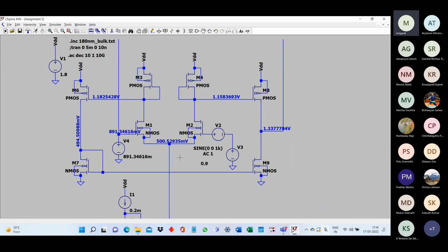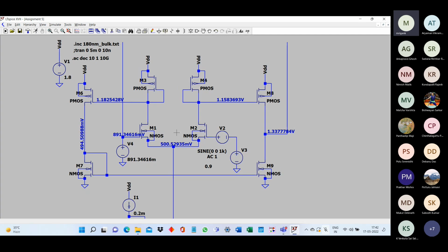Right now you see the bias current in the first stage has been increased, and that basically means the VSG of M3 and M4. If you look at the VSG of M3, M4, that is continuously increasing. As the bias current is increased, now the VSG is almost 0.7 volt, right? So if this is 0.7 volt, that means once again for the output stage, the VSG of M8 has increased to almost 0.7 volt, whereas the VGS of M9 is remaining the same.